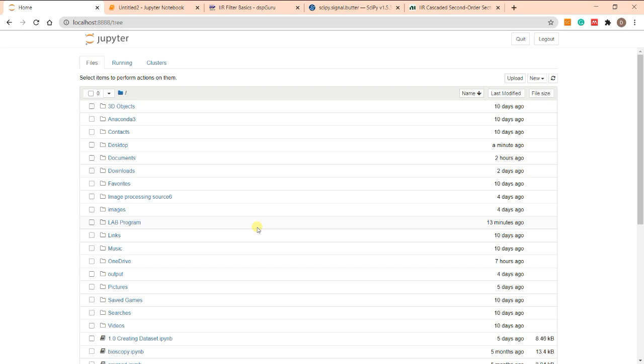In relation to different filters, the FIR filter is a little bit unidirectional. In the signal flow graph, if you see it, nothing is coming from feedback. It is only from the input to the output side. But in the case of an IIR filter, we have a feedback path.